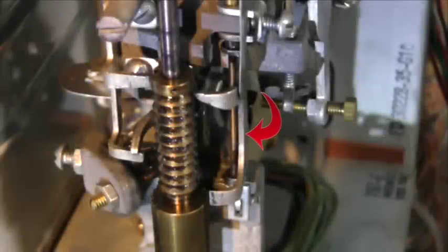This is the double dog, so called because it has two functional legs. The upper leg engages the vertical ratchet teeth to prevent the shaft from slipping down between pulses during vertical stepping. The lower leg engages the rotary ratchet teeth to prevent anti-clockwise rotation of the shaft between pulses during rotary stepping. After rotary stepping has finished, the lower leg also holds the shaft stationary in its off-normal position for the duration of the call.